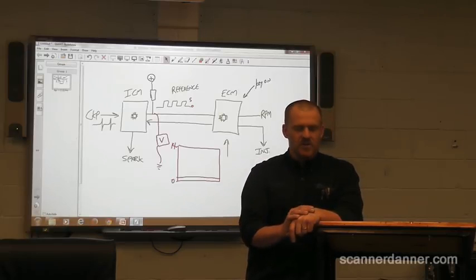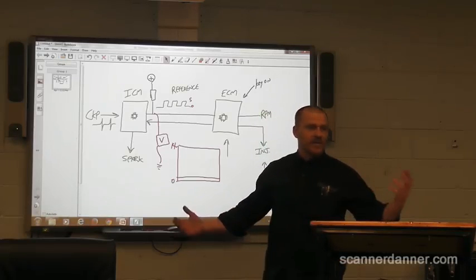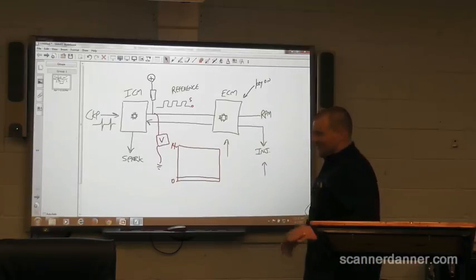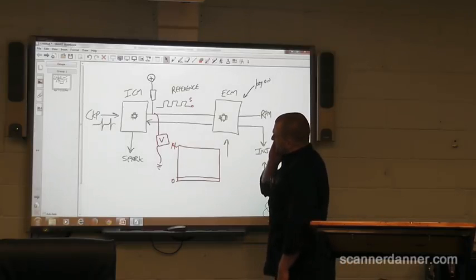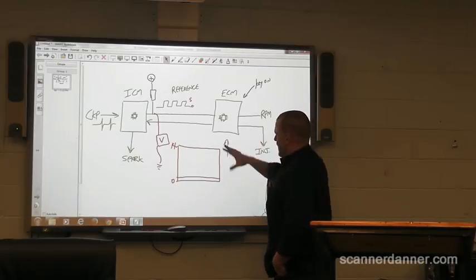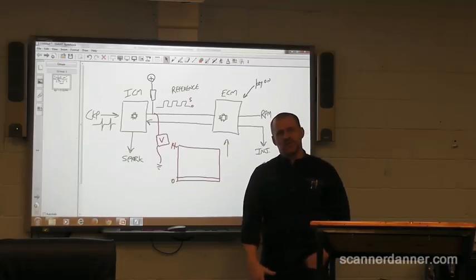So I go back and look at the truck. By the way, I don't charge for those. If I got to go back, I got to eat it, however long it takes. So I go back to the truck and I redo these tests, and same thing. I'm like, wait, why is the test light working? And when I connect my scope, I don't have a signal. And I thought about a short to ground. You see where we are now.